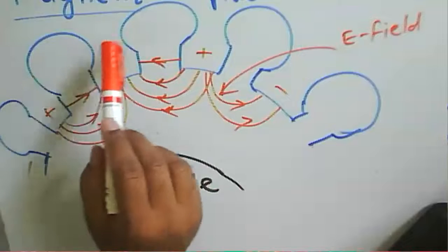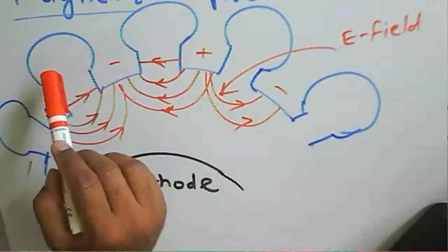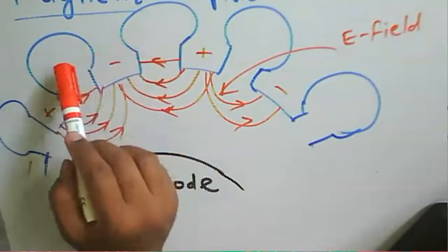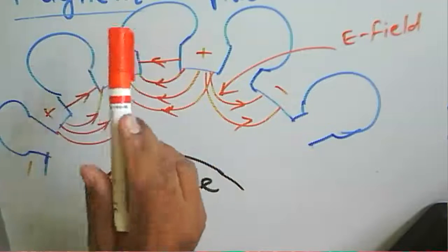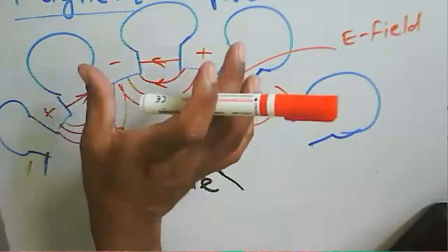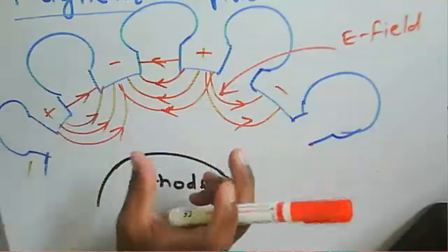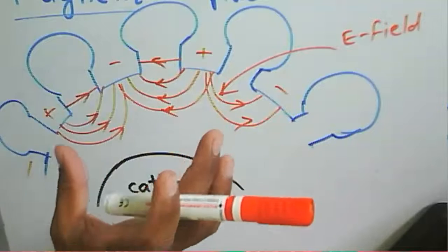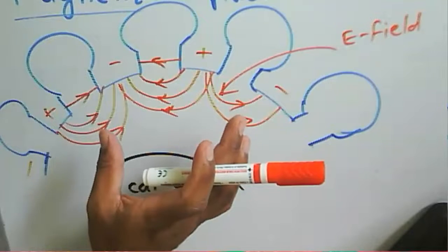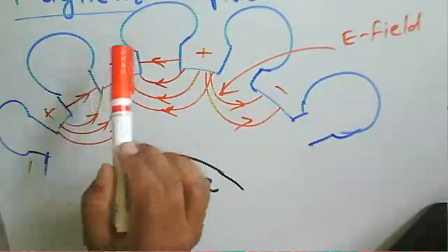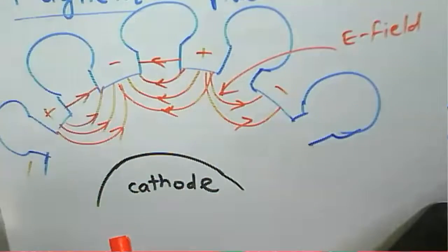If the phase difference between the adjoining cavities is pi, then the magnetron is working in the pi mode of operation, and in this pi mode you will get the highest efficiency and the oscillation will be stable here.